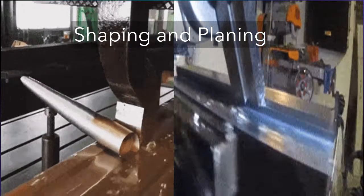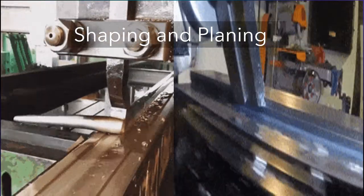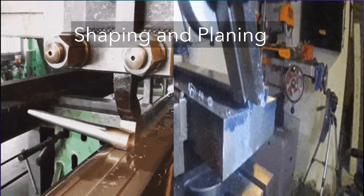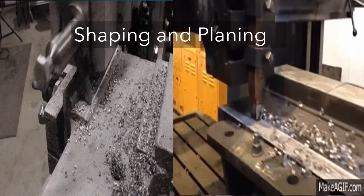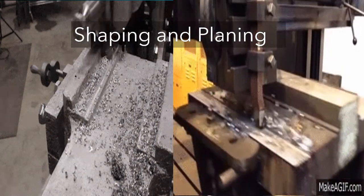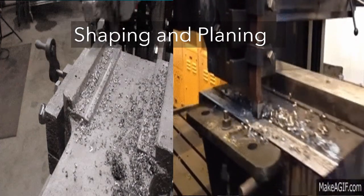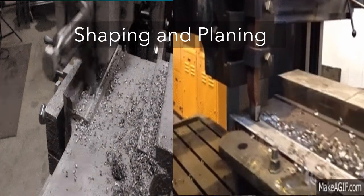A single-edge cutting tool is used in interrupted cutting operations in both shaping and planing. The tool is subject to impact loading when entering the work. Typical tooling is a single-point high-speed steel tool. Cutting speeds are low due to the start and stop motion.